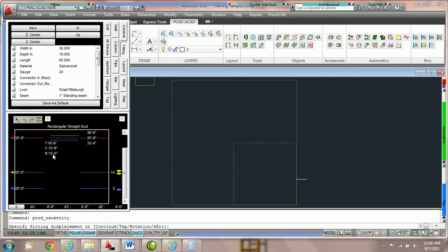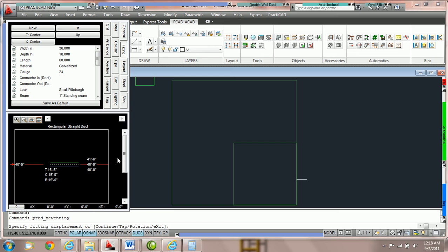For example, they say 15 now because the bottom of duct is at 35 foot. That's where we're holding it in absolute. So it's 15 foot above 20 foot, or relative bottom. However, if we switch our new relative mark 1A to relative bottom, you'll notice that these values will change. So if I were to put 15 foot in here now, that means 15 foot above whatever relative bottom happens to be at that point in time. So if we've set 25 foot to relative bottom, and we said be 15 foot above it, we're at 40